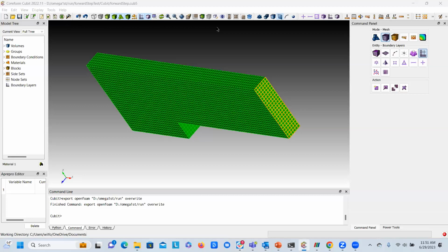And then how does Cubit handle complex geometries? For example, boundary layer generation for high Reynolds flow simulations. Do you have examples of such grids? I don't have any on my machine here, but I do have examples of using those. Again, the way you handle it is you go in, you identify the boundary, and you put in a boundary layer.